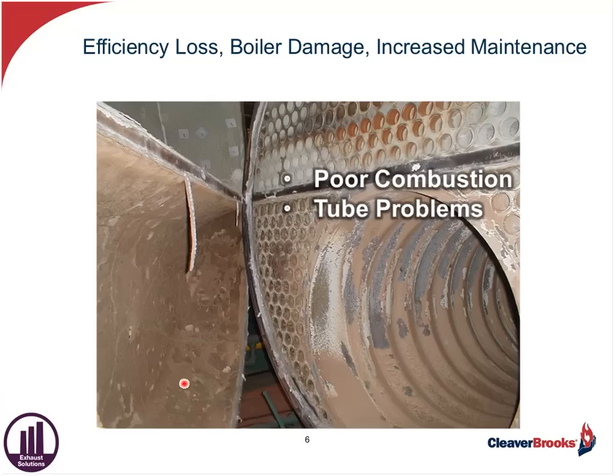What they did is they added another boiler downstream of it. They ducted it into the breeching before it hit the stack, and this caused a lot of back pressure because we had increased mass flow in that breeching. It caused a huge pressure drop, resistance to flow. That impacted the fuel-air ratio, and we started sooting up.